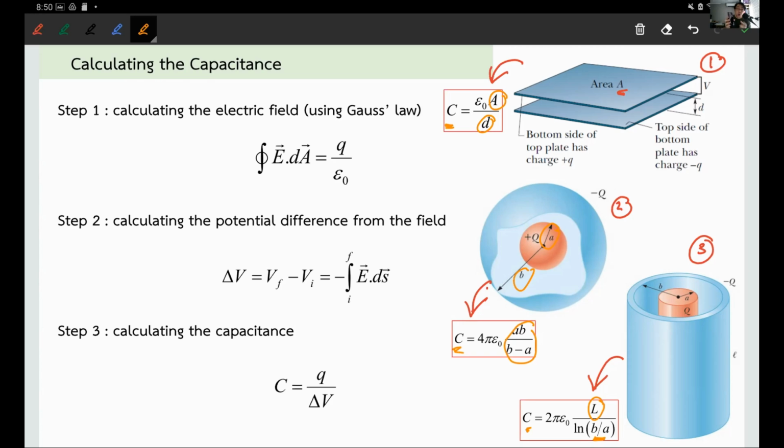And with that, you don't need to touch it, right? Because that's the key. You just have to change the physical configuration around that capacitor. So by having your finger close by and not having your finger close by, the C on those pixels will change. And that's how you detect which portion of the screen gets touched.